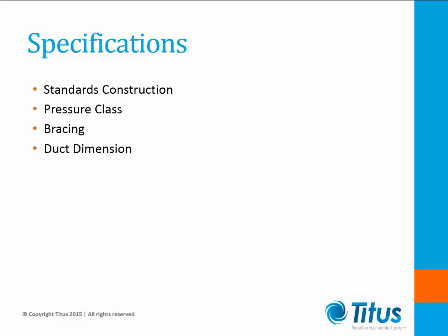When selecting pressure class, remember to review the fan selection maximum static pressure available. It will be higher than the design point. If there is a control malfunction and terminal units on a VAV system are closed, the primary fan could ramp up above operating conditions and damage the ductwork, causing a costly repair.